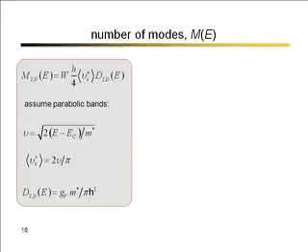You might remember in silicon, in the conduction band, there are 6 equivalent valleys. When you quantum confine them in 2D, there tend to be 2 equivalent valleys in the lowest set of subbands. You always have to ask yourself, how many equivalent valleys are there? And for that, you need to know something about the band structure of the material that you're talking about.